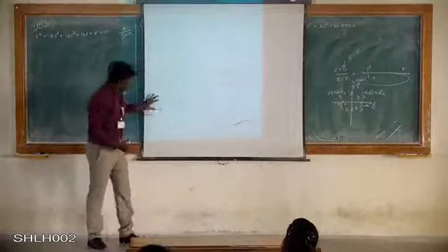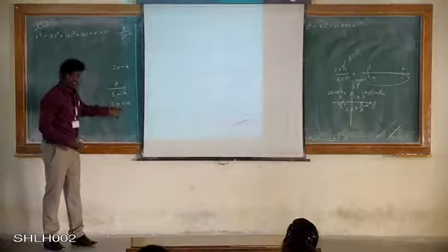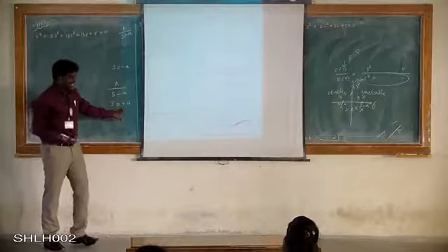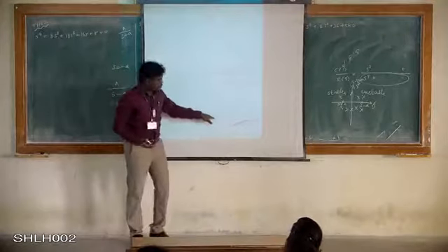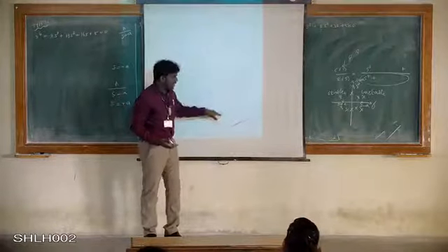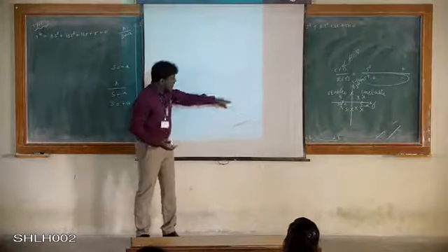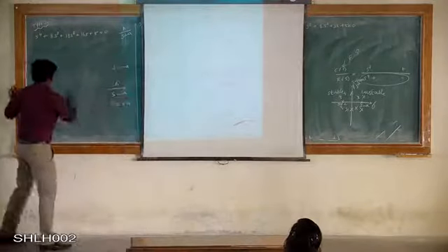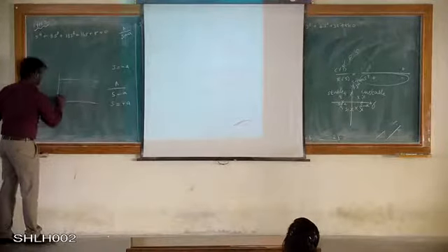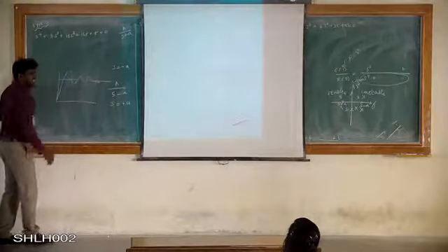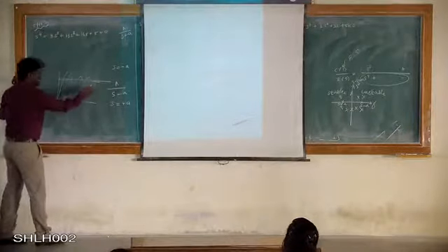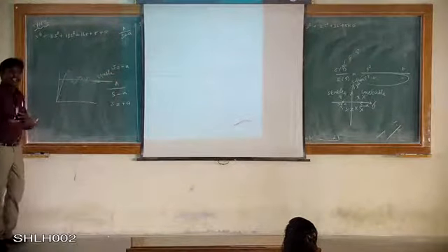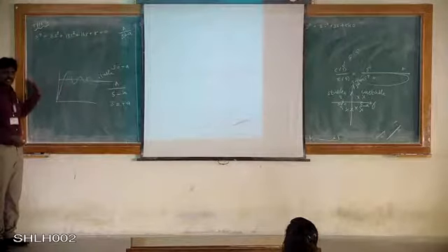I repeat. If your root has S is equal to plus A, then it will be lying on the right half of the S plane. If it is lying on the right half of the S plane, your plot is going to be like this, right? So, it is exponentially increasing. If it is exponentially increasing, you will not get any settling, right? As far as we have analyzed, this is the system where your waveform will settle like this. If it is settling, then the system is stable. If you are not getting the output like this, then the system is unstable.